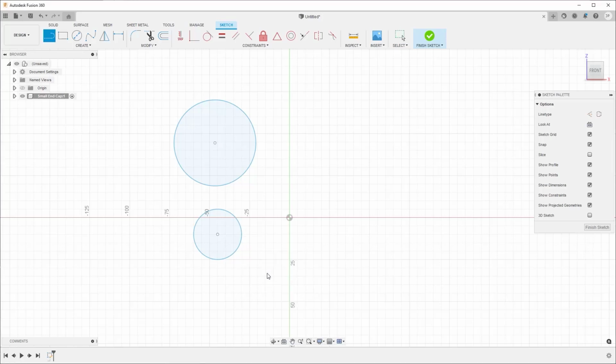If you hover over existing sketch geometry, blue auto snap markers display to help you snap to the geometry. If you snap and drag away from certain geometry, a dashed blue tracking line appears to help you align geometry as you sketch. If you want to temporarily disable these auto snap features, press Ctrl on Windows or Command on a Mac while you sketch. With the auto snap enabled, you can add other geometry types to existing geometry by snapping and left-clicking as needed until you get the base geometry you are after.